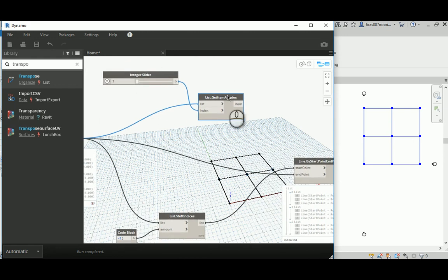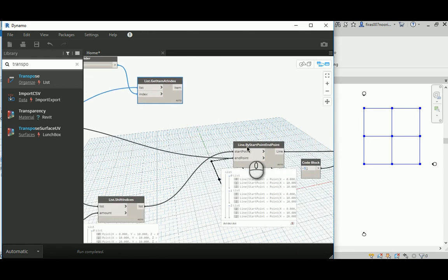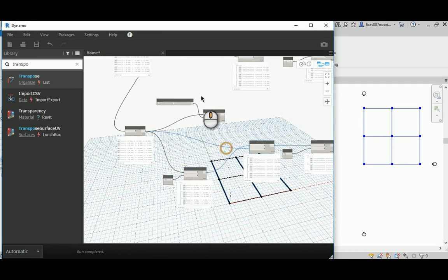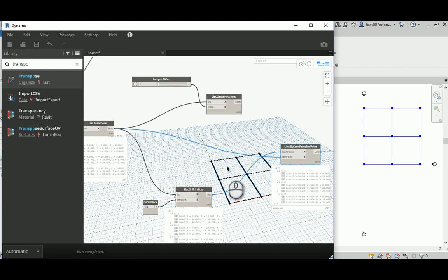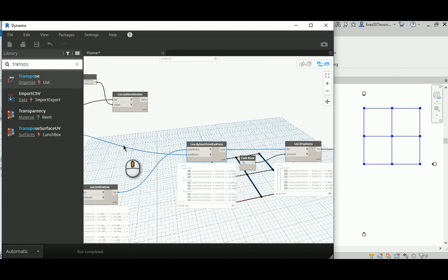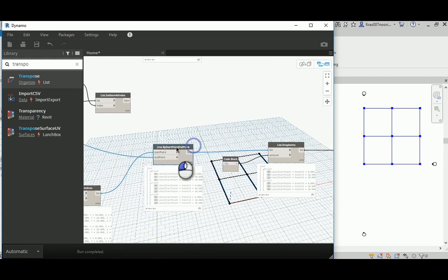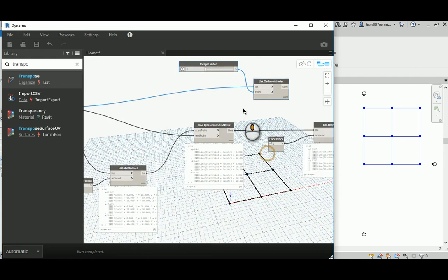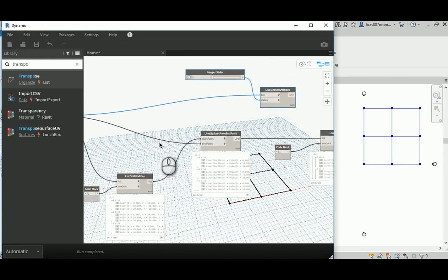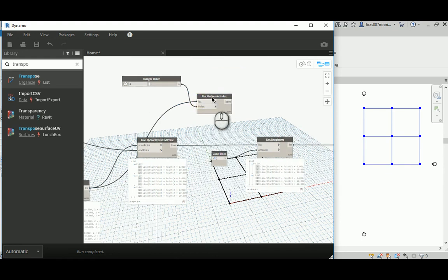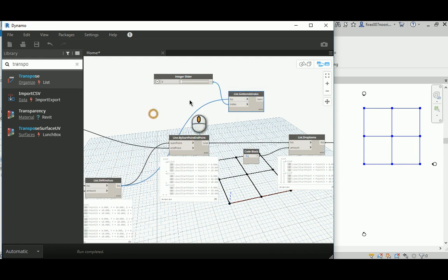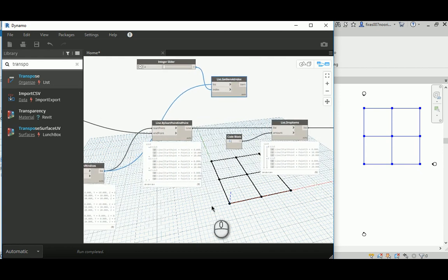Thank God we have this testing loop, and it was making crazy things before because I connected this one to the upper vertical loops. So you have to select this one with this one, horizontal with horizontal, vertical with vertical, don't forget. Otherwise you're going to get these creepy results. Now, what do we have in here? Of course, extra lines. 3 groups, right? If you don't believe it, just connect this again and hit 2, and you're going to see these ugly lines. Those are just making a third line from the beginning to the end.